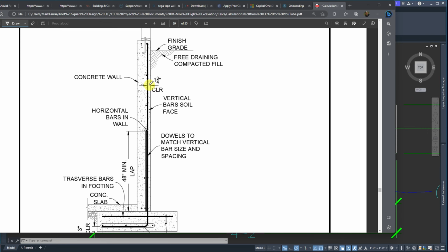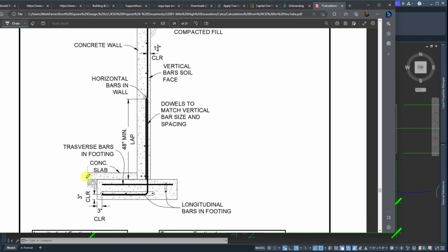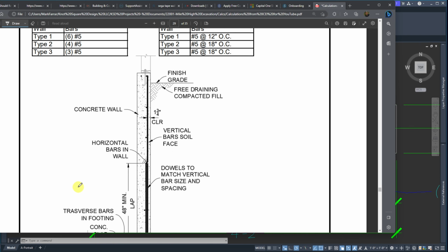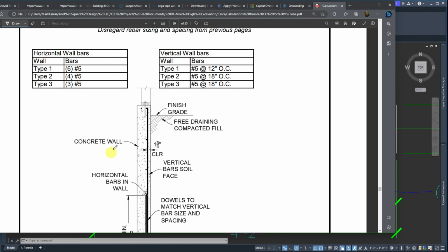So basically all the information we need is here. And then we need 1 3/4 of an inch of concrete outside of the steel, and that's to help prevent corrosion. 3 inches min, and down in the bottoms, it usually is 3. I think the concrete industry is a lot of that's spec'd too, so you might see that a lot too. So that is what we're going for.